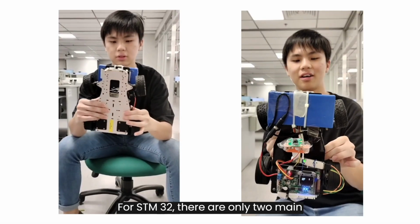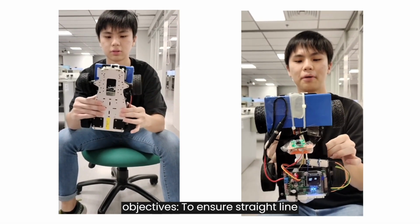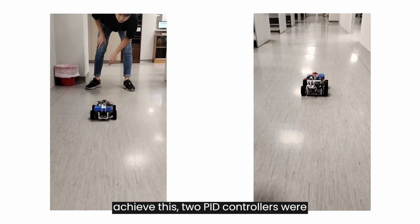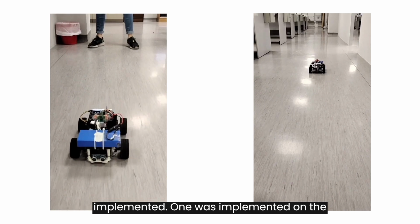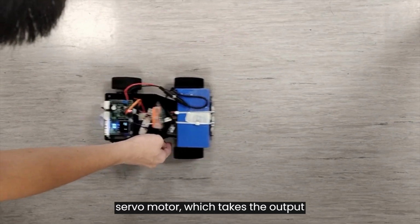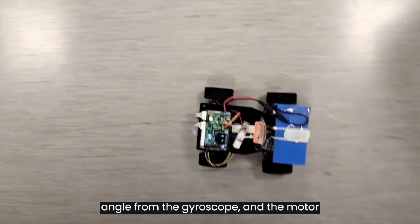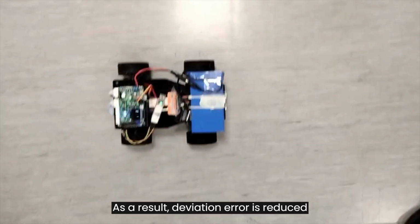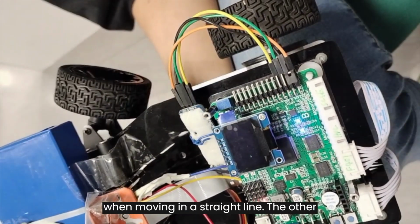For STM32, there are only two main objectives: to ensure straight line motion of the car and accurate turns. To achieve this, two PID controllers were implemented. One was implemented on the servo motor, which takes the output angle from the gyroscope, and the motor constantly tries to realign itself to achieve the desired straight line angle. As a result, deviation error is reduced when moving in a straight line.